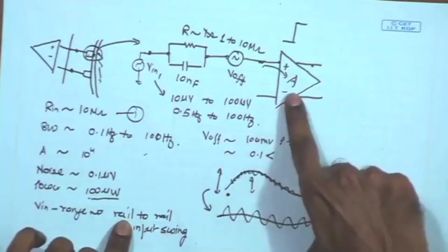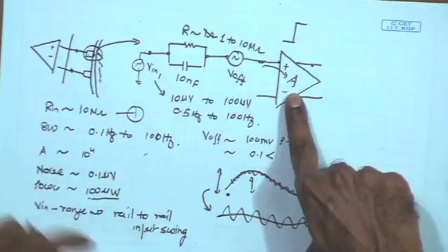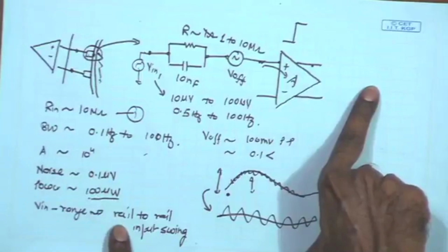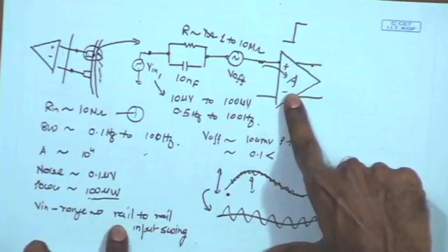If we choose a particular configuration of the front end amplifier, some configurations can give us a larger swing, or it can be closer to rail to rail swing. Some other topologies may be better for some other parameters, but they can limit the input swing. So, there the topology level choice also comes into the picture. What topologies to choose for the particular amplifier, so that we are meeting the input range criteria as well.